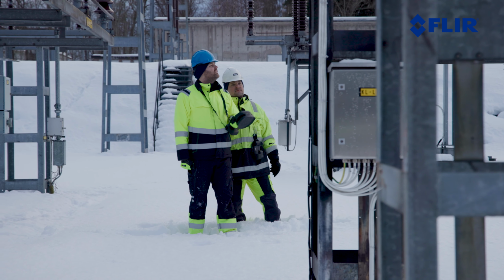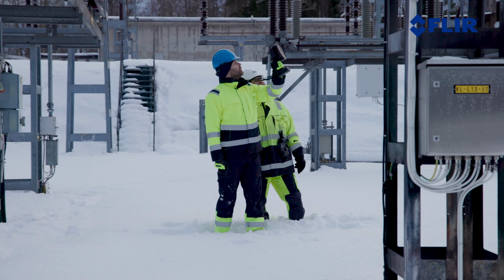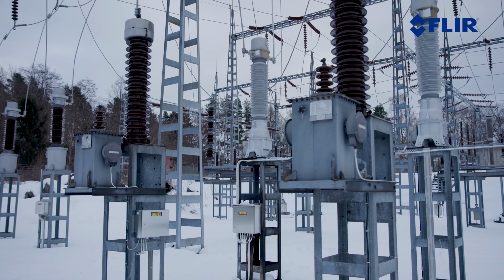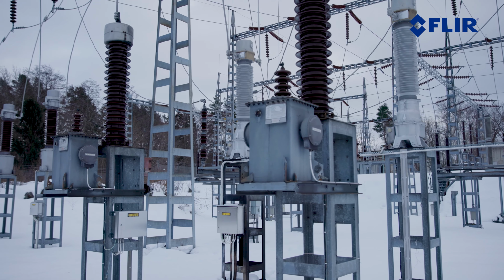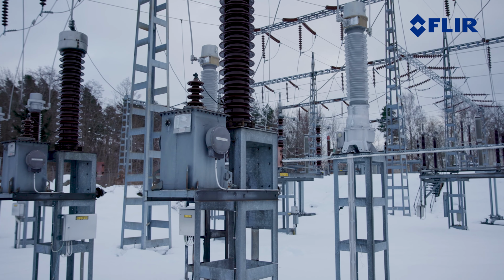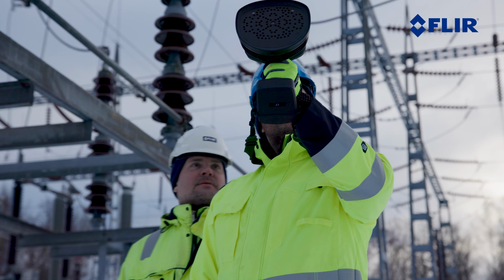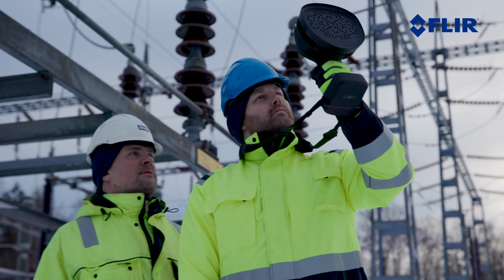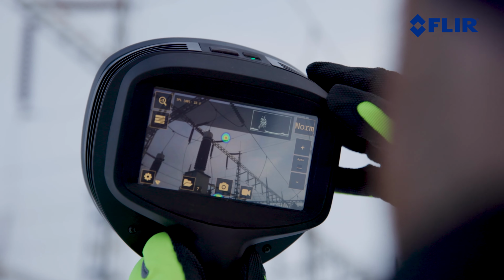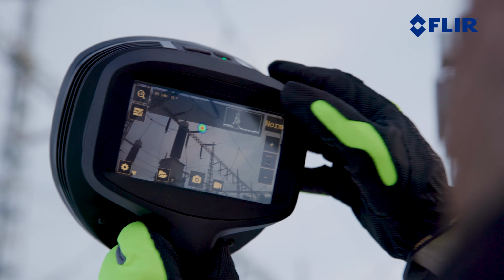When an electric component begins to fail, one of the first indicators is sound. In fact, sound usually appears before the components begin to heat up. This sound is caused by partial discharges that signal the harmful flow of electricity and deteriorate components over time. There are several different types of partial discharges, some are harmless while others indicate problems that may eventually lead to catastrophic failures. Early recognition is critical, as corrective measures can then be planned accordingly before critical failures occur.